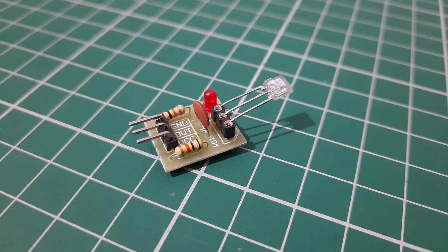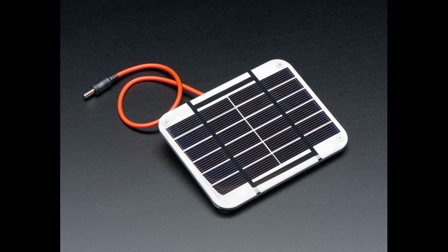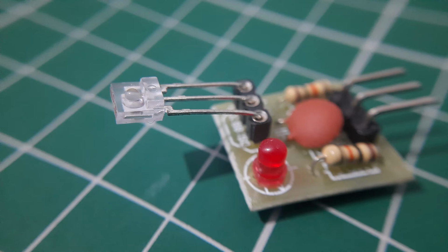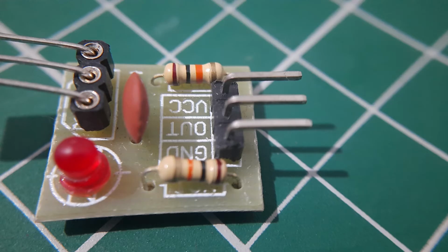Now coming to the receiving unit, we need a sensing element to sense the varying amplitude of the laser beam. Here I am using a laser receiver or laser sensor for that. You can also use a solar panel, but the laser sensor produces better output than the solar panels. It has 3 pins, the signal, 5 volt and ground. If we connect the signal and ground pins to the terminals of a speaker, we can hear an extremely mild music.